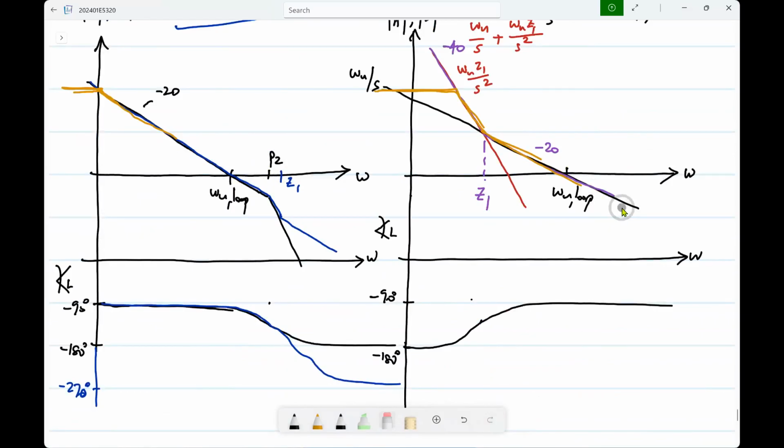In reality, there will be some other junk, but the highest possible unity loop gain frequency is higher for the feed-forward op-amp compared to the Miller compensated op-amp. So that is also another advantage. Is this clear? So the feed-forward topology, because of its higher order behavior at lower frequencies, gives you loop gain advantage, and it also gives you the speed advantage.